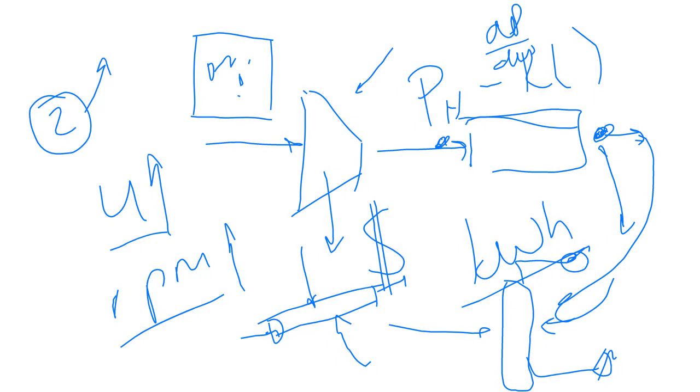After Theme 7, I will show you some tricks of how to test very quickly whether you need to bother with external diffusion effects. Okay, so for your design application, when you do the designs, you will have to prove to me that you've thought about it in two separate discussions. One, when I evaluated the rate equations that were supplied to me, did I make sure that that guy did his job, because rates that are published that were subject to external diffusion effects are useless to you. You cannot do anything with it, right?